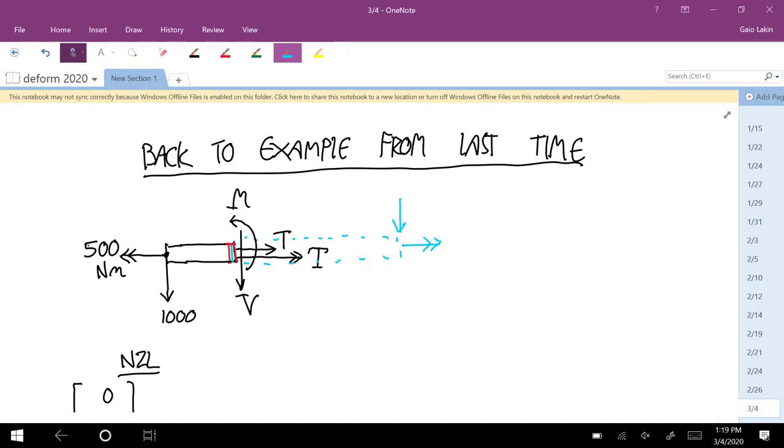We're only dealing with the loads acting on the right side of that sliver. So we're only using the sign convention of the right side. And then we go all the way from the far end to the point that we care about. So these are still the external loads. The only internal loads are on the right side.